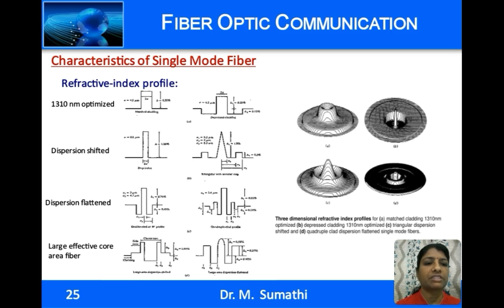Next is the dispersion flattened fibers, where the dispersion is flattened over a wide range of wavelengths. Then we have the large effective core area fiber, where the core area is made large enough so that nonlinear effects are minimal.